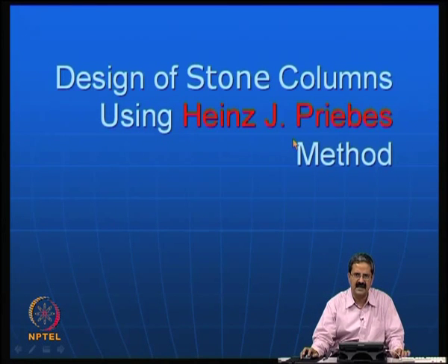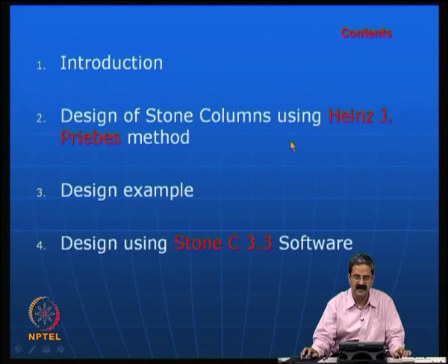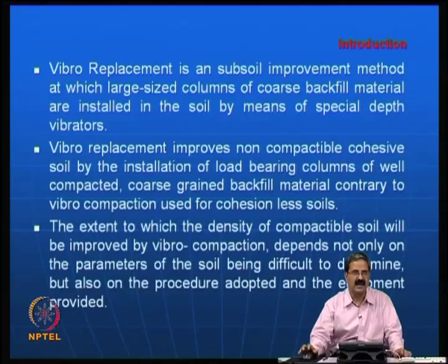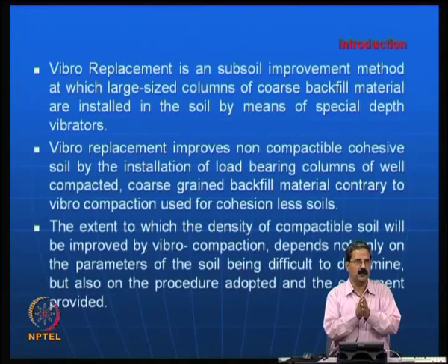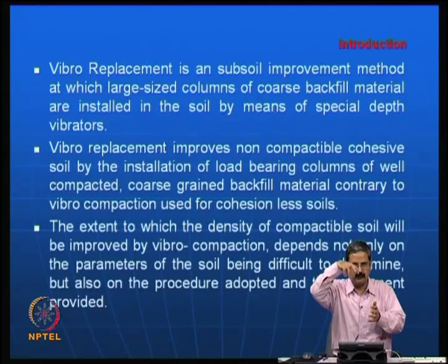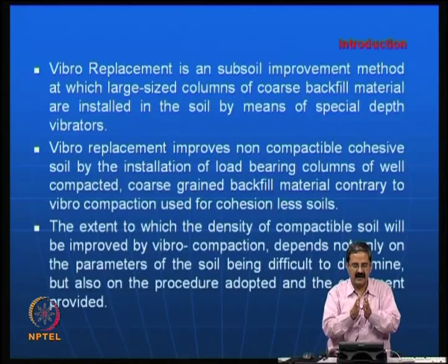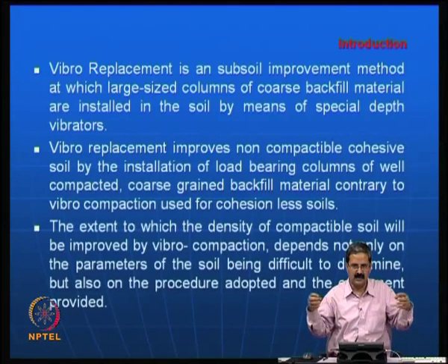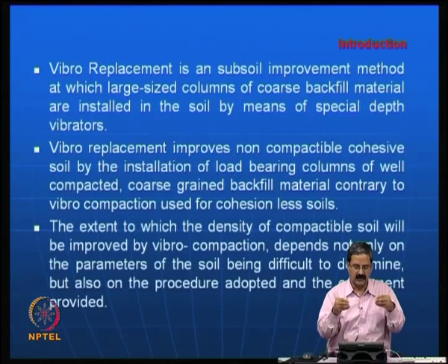Actually, I would like to describe one design method that is very popular, used by Keller and other companies. This is a very innovative method as well. In fact, there are many design methods, one using the limit equilibrium method, another the elastic analysis approach. In the limit equilibrium approach, what we did was use cavity expansion: we put a cavity inside, allow it to expand, and assume there is a resistance from the soil. So, we are trying to equate the passive pressure and the load applied.